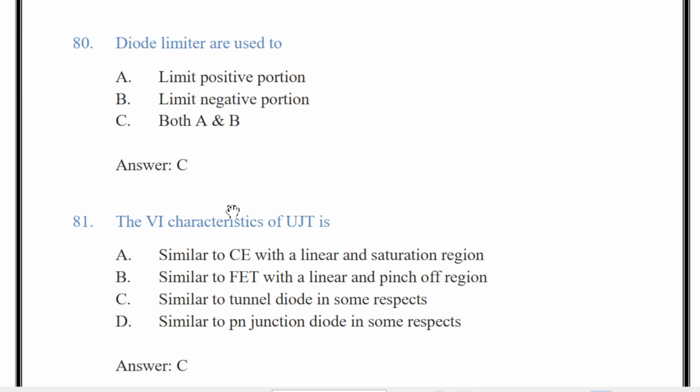The diode clipper, also known as a diode limiter, is a wave shaping circuit that takes an input waveform and clips or cuts off its top half, bottom half, or both halves together. This diode clipping of the input signal produces an output waveform that resembles a flattened version of the input.